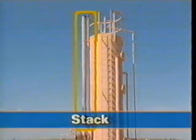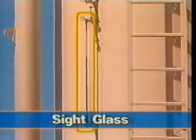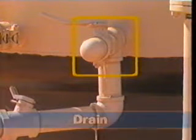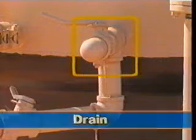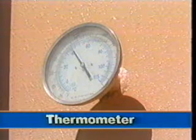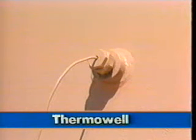This metal cylinder, called a stack, vents the exhaust gases after they pass through the fire tubes. Sight glasses allow the pumper to monitor the oil-water interface within the treater. This helps maintain proper levels and efficient operation. Located on the bottom of the heater treater, the drain allows emptying of the vessel for repairs or removal of accumulated solids. The thermometer indicates the temperature at which the emulsion is being treated. The thermal well provides a location for the temperature probe. A thermostat connected to the probe maintains the preset treating temperature inside the vessel.